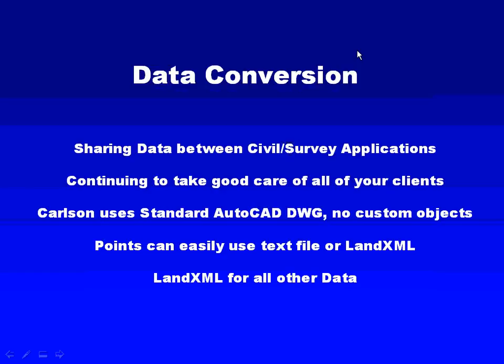As far as civil survey data, one of the key data types, of course, that we work with is point data. And a very common way, and still a real good way, is to just export your point data to a text file, a PNEZD, comma delimited, or whatever format you like. Write it out as a text file, and that can be imported, of course, into any other software. That's one way to go. It's surefire. It's guaranteed. It just always works, always will. And, of course, we obviously facilitate that, and that's one way to go for point data.